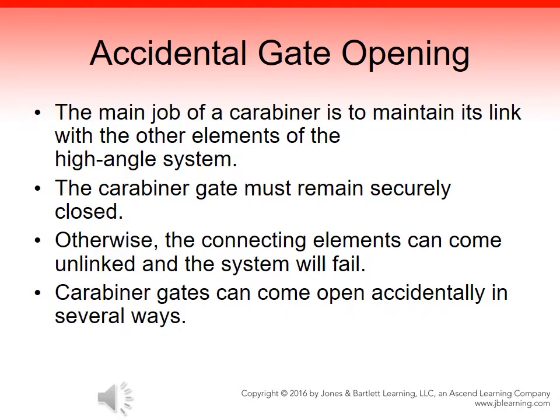The main job of a carabiner is to maintain its link with the other elements of the high-angle system. The carabiner gate must remain securely closed. Otherwise, the connecting elements can come unlinked and the system will fail. Carabiners can accidentally become open during rope rescue operations.